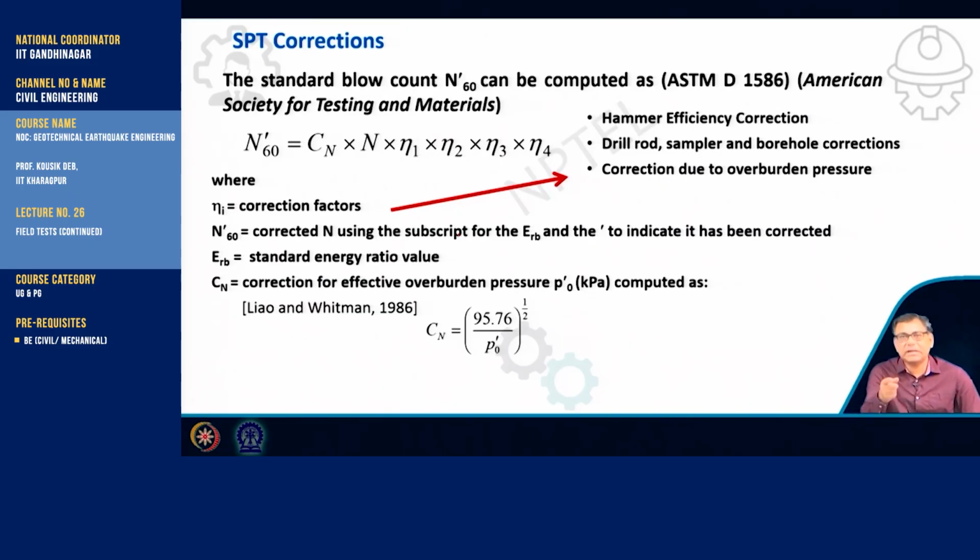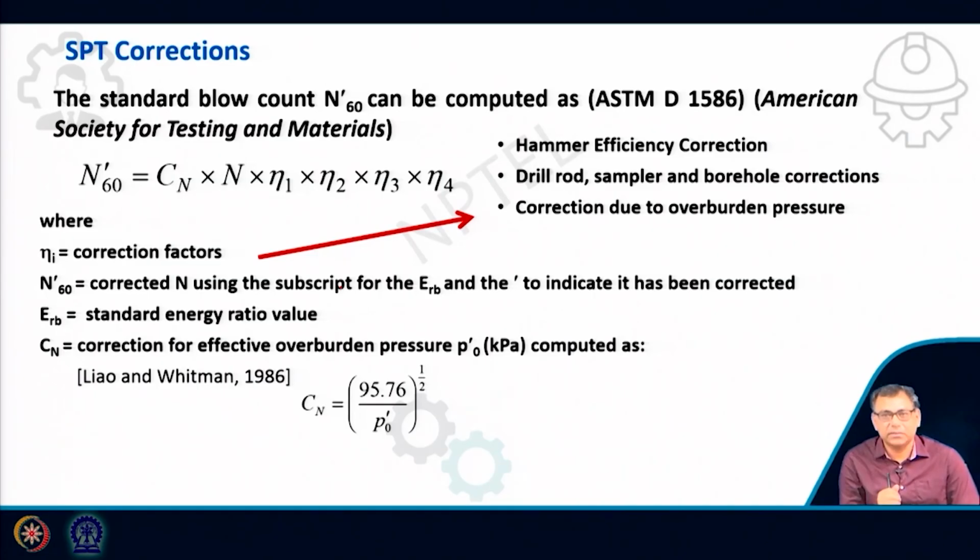But when you represent them, if your energy is different, different N values will be there. Suppose some tests are done under 80% energy and some under 60% energy; we cannot represent them with respect to different energies. So you have to convert it to a single energy value, that is 60. That means 60 means this test is done by applying 60% energy.